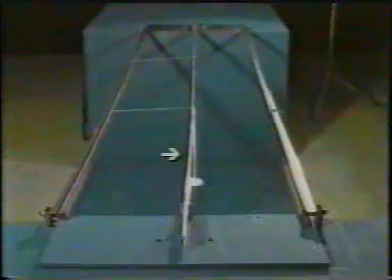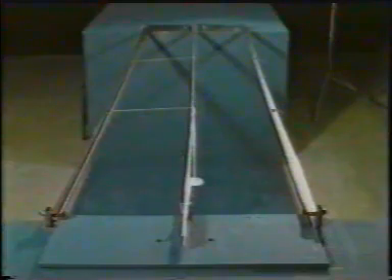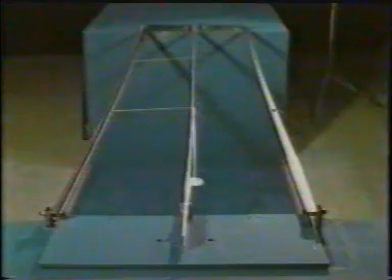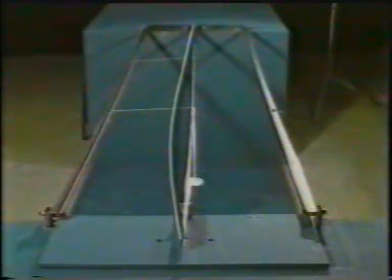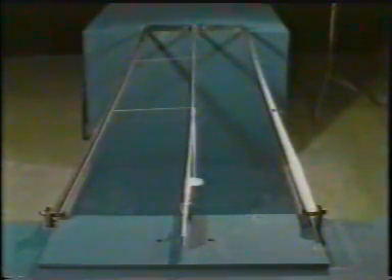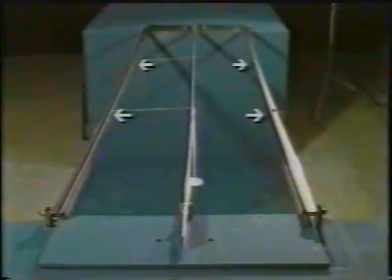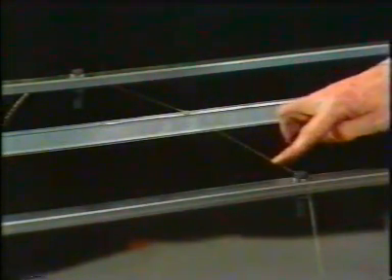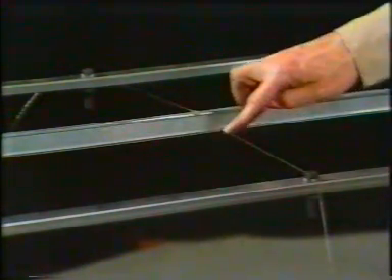An alternative way of increasing load carrying capacity is via the provision of bracing. Consider again a slender, simply supported beam. If it were unbraced, it would fail by instability, with buckling occurring over the total length of the beam. Bracing is introduced at the third points and attached to stiff framing. This bracing is in the form of light, flexible wires.